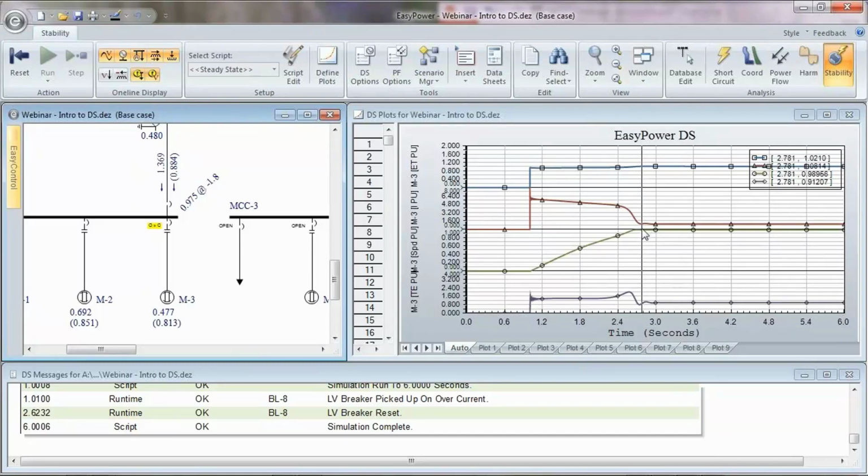Okay, there we go. So 3 minus 1 is 2 seconds. It took us twice as long to start by doubling the inertia. So that's a key value. You see, those are some key values in that data. But again, we're going to put typical data values in there for you, and we're going to put a typical inertia value. If you want to really get much closer, then you have to start adjusting each of those parameters to get it closer to what your motor actually is.